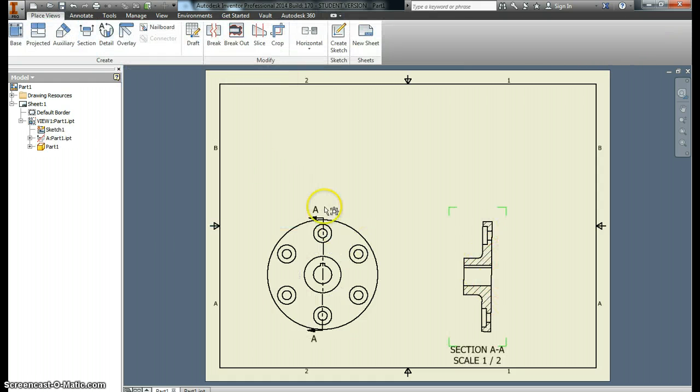and that is the section view as if we use this cutting plane line to cut through this part and look at the inside. We're looking into the left side. That's what these arrows indicate. And that's what it looks like on the inside. Now, I do have an issue with mine. It's not perfectly vertical, so you would want to go back and fix that. I'm not going to worry about it right now since I'm recording.